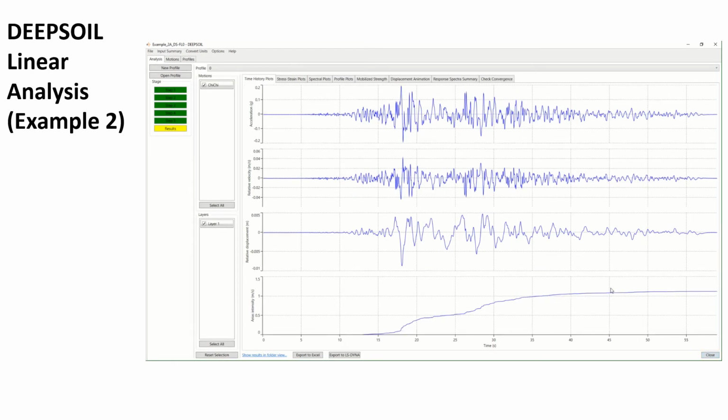There is a significant difference compared to the previous plot that we obtained with undamped properties. We still have damped properties for the soil layer, but the difference is that the bedrock is elastic, so there has been some dissipation of the energy by going back to the bedrock. As you can see, we don't see that dramatic value of acceleration over 2 billion G, which was unrealistic.